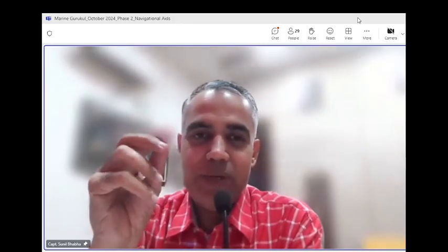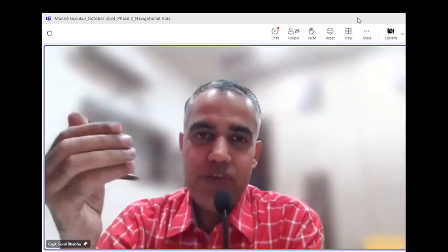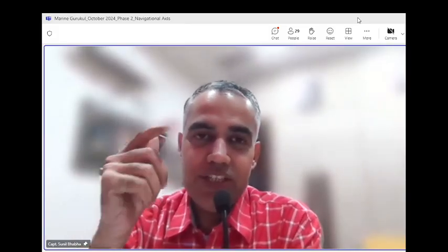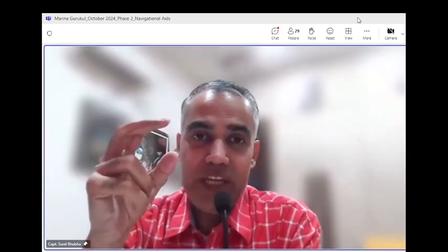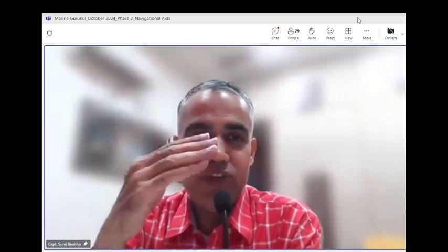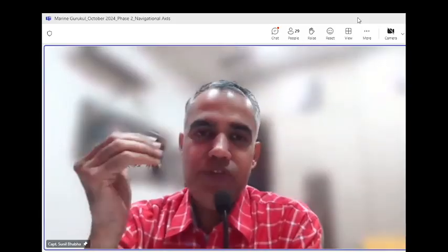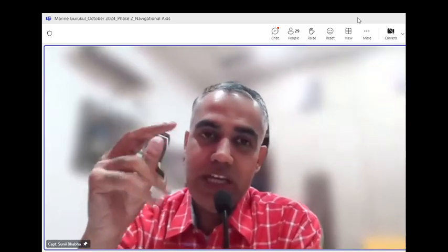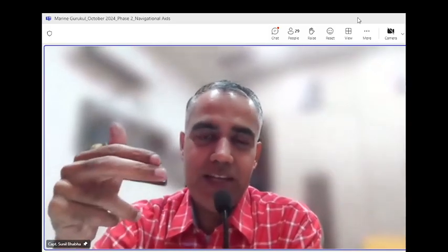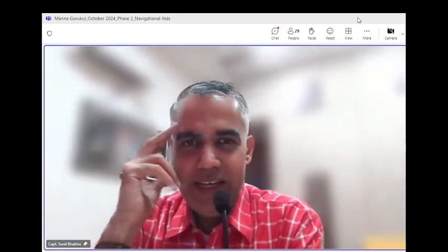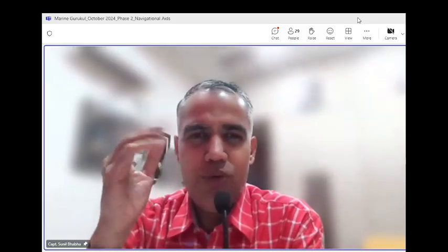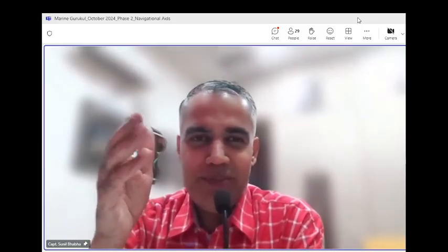And the second reason, son, we will pick up later once we do the coefficients. It is known as heeling error correction. This heeling error is the main cause of change in deviation when you change the hemisphere. With a hemisphere change, the heeling error correction gets disturbed and needs to be redone again.